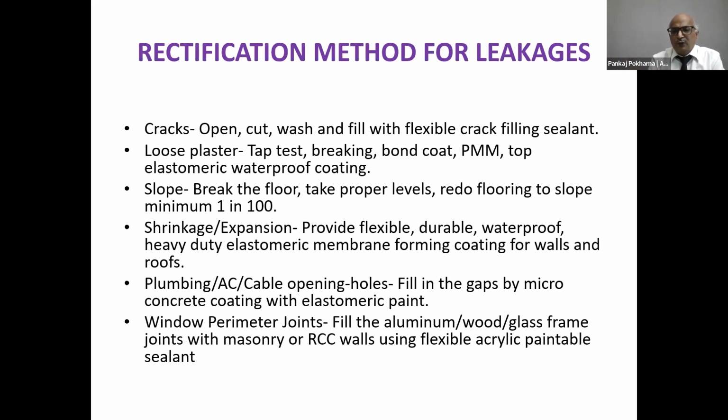What you need to do is, before that, you have to have a checklist. So, pre-monsoon preventive measures, what should be the checklist? What should you do right now at this stage? First of all, inspect the terraces and the rainwater pipes. If the rainwater pipes are choked, you have to clean them up before rain, put water and check that the rainwater pipe is not completely choked and the water goes away. Secondly, you have to check the levels.